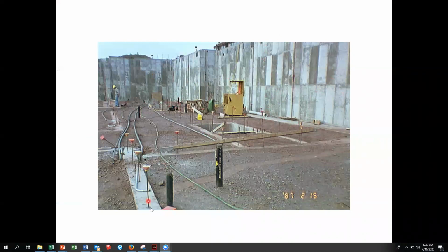These are all the interior footings. These are all the dowels that are going to go into the block walls, because in that ground floor with all the labs, they're all block walls. And this is actually the elevator shaft right here. All of these are conduits, because all of the rough ins, the electrical, the MEP, mechanical, electrical, plumbing, have to be installed before you place the concrete slab. So here's some waste piping, electrical conduit, and so on.